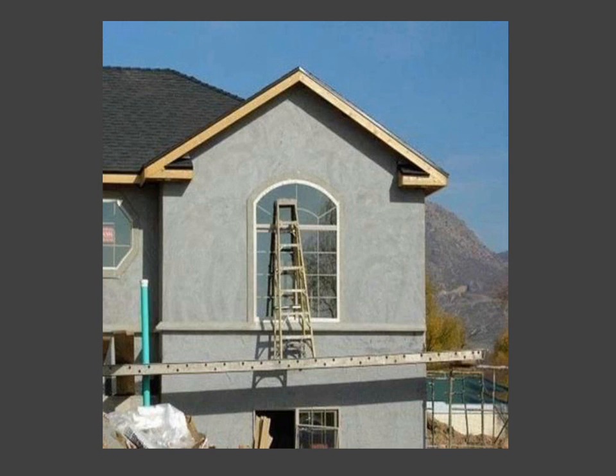Okay, here's an example. You see this kind of thing all the time. Guy's got himself up a scaffold, and on top of the scaffold he puts a ladder. Now, if you take a look at it, there's all kinds of violations here. Not only does he have the ladder on the scaffold where it can fall off, but it's an A-frame ladder, which you can't use unless it's opened and latched. It's closed, standing up there. Why don't you want to do that?